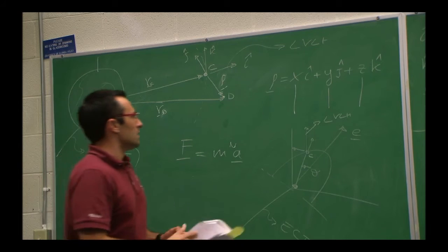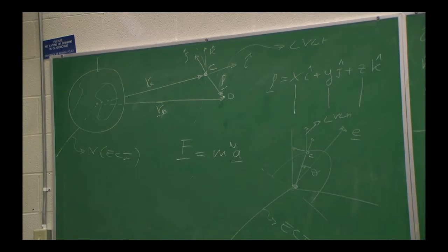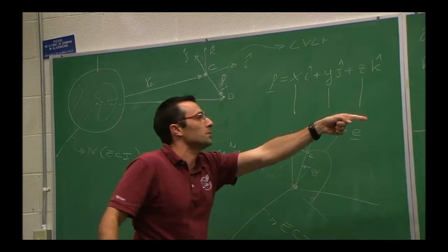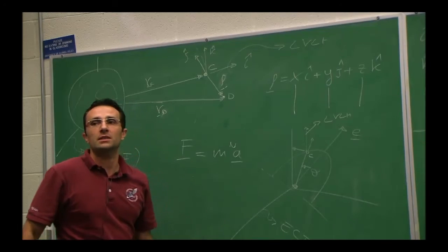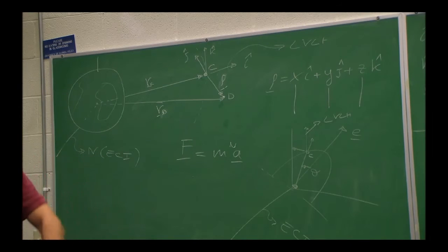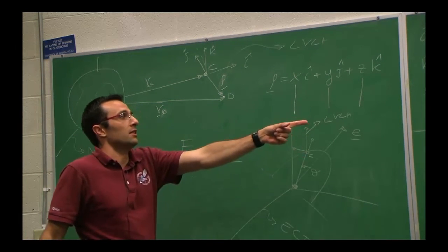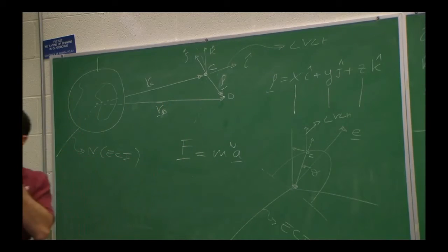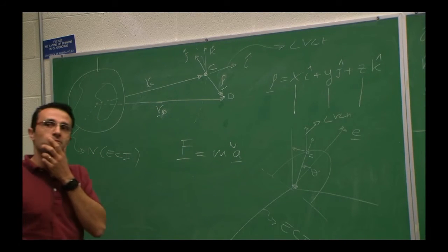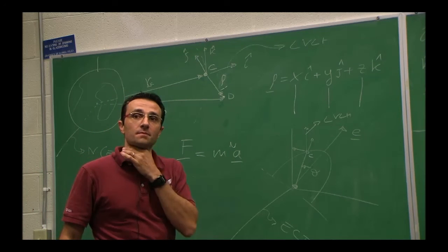Of course, this vector is the angular velocity of LVLH with respect to n. If you don't like it expressed in LVLH, and I wouldn't see why not, because everything here is expressed in that basis, but if you want to go to the basis in ECI, then you will have to transform that vector back into the ECI basis. Good luck with that. There is the 313 rotation plus the theta rotation. You can do it, but let's not make your life very difficult. You already have a basis where you can see that the angular velocity is theta dot K. Make sense? No? You can tell me if it doesn't make sense. It's not so immediate.